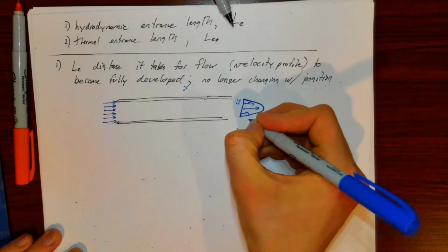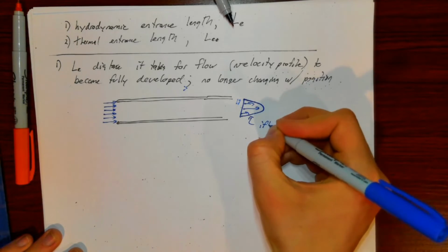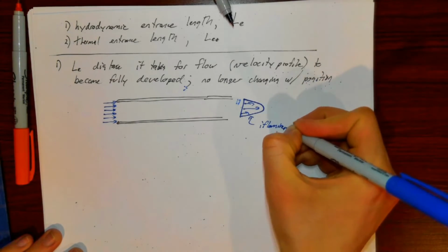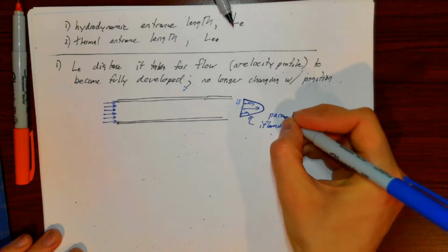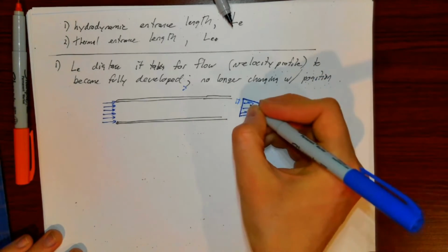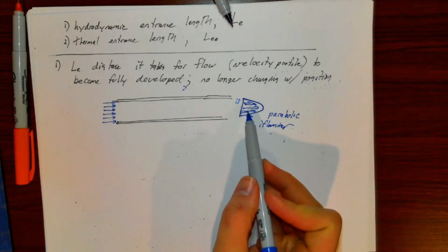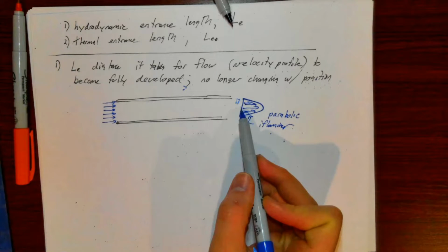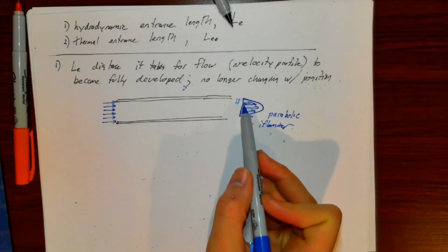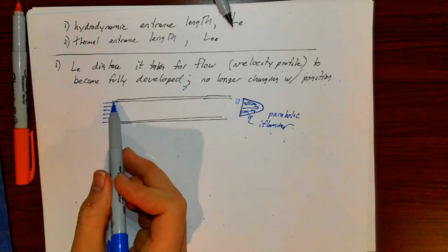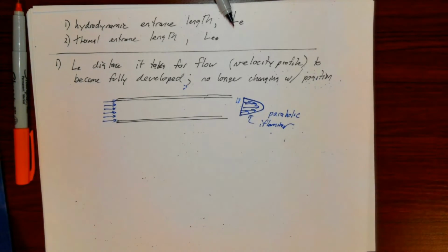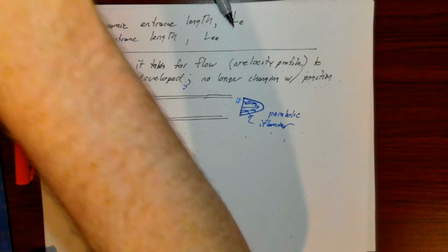if laminar, right? So we end up with a parabolic velocity profile if it's laminar. And if we think about it, in the middle the fluid is actually sped up a little bit, and at the edges it's slowed down a lot, compared to its originally uniform counterpart. So what's going on there?